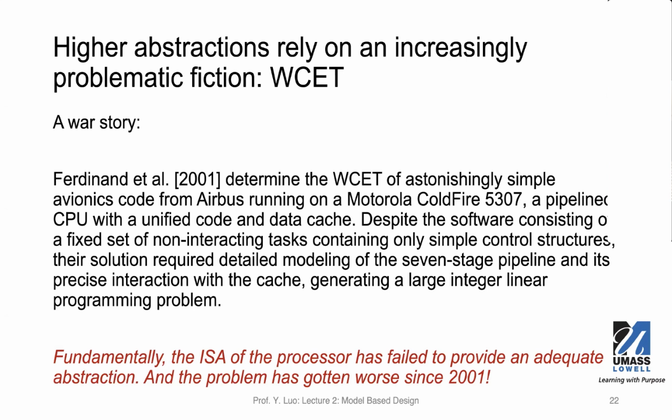Such an assumption is dangerous because it depends on where the data resides. If the data are already cached in this on-chip cache, of course you can have faster execution time. But if the data are mostly off-chip, then you have to load data from the off-chip memory onto this processor for computation. In that case, the execution time is actually a lot longer than what we saw earlier.